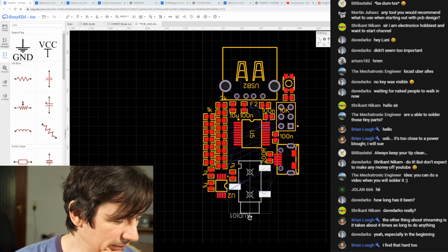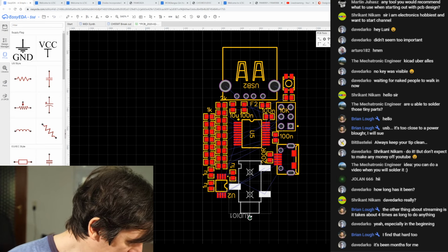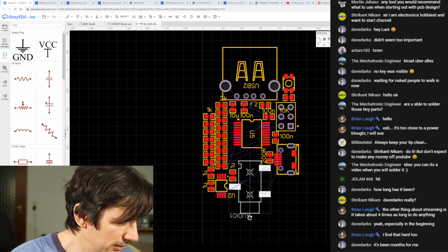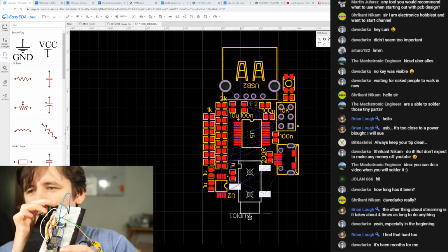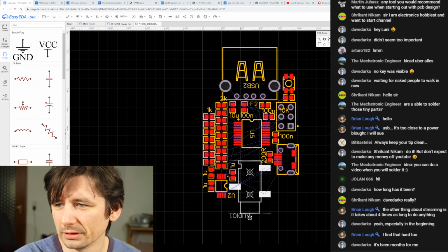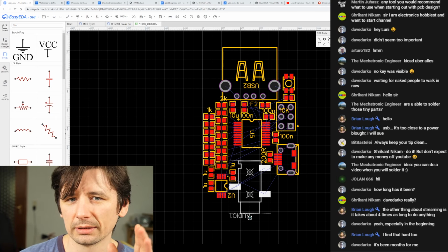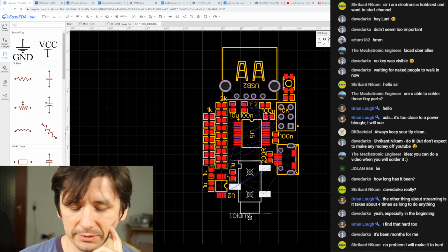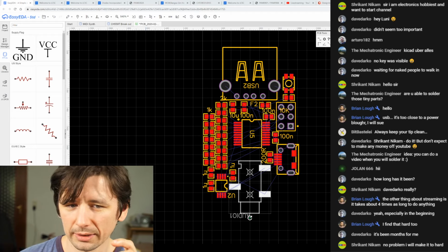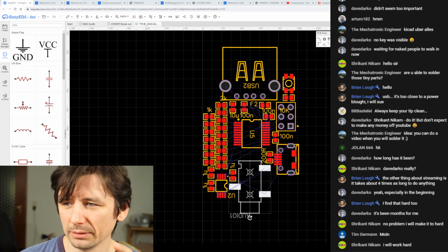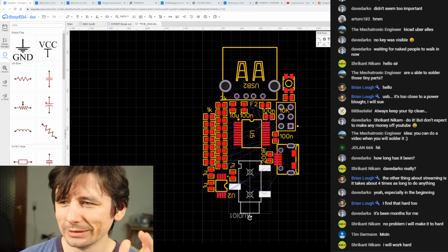I could even use your help, since there are some experts watching me. On Friday I was really struggling. I have this analog PAL video working with the internal digital to analog converters, and now I want to get it working with the second I2S channel, since I can use 8 bits there, and I even have a fast buffer and these R2R resistor ladders, and it simply doesn't work. The color carrier doesn't work, and I'm really struggling with this.